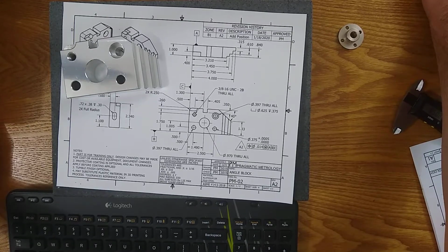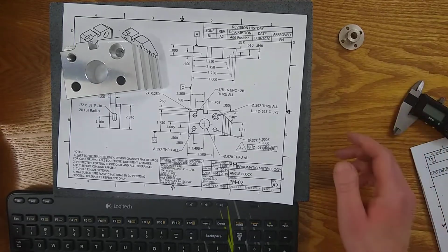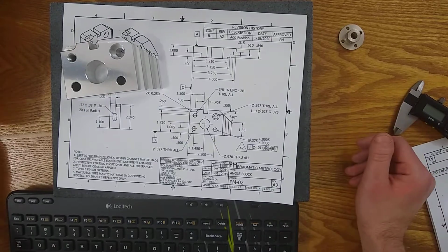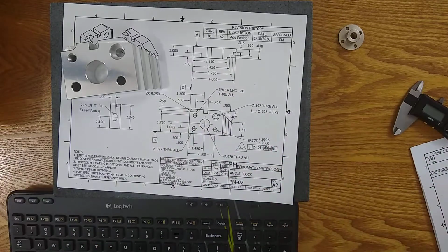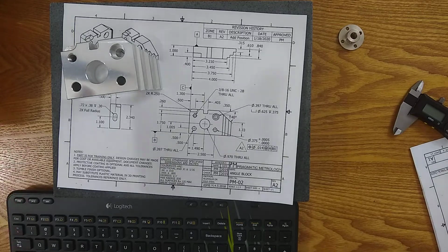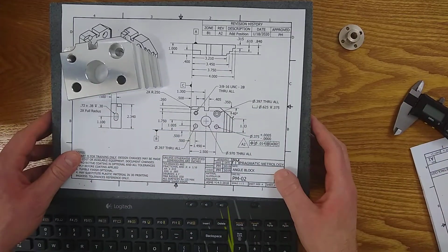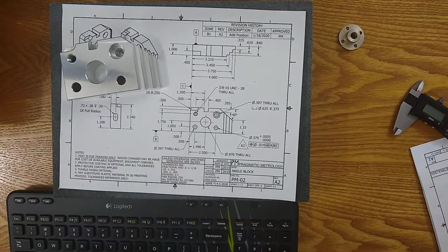So this has a form error of 8 thousandths, and that is larger than the tolerance zone. 8 thousandths is larger than our plus or minus 1. So 8 thousandths definitely means it's out of tolerance. We don't even need to know the numbers. If you see a variation bigger than the tolerance zone, it's definitely out of tolerance. So this feature fails. This is an implied error. If you look at the print, it doesn't have it. 970 plus or minus 1 doesn't have any GD&T with it, but it would fail the print.